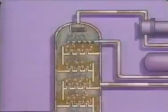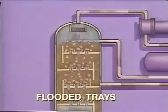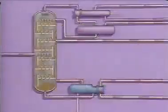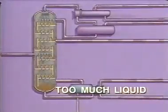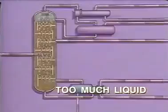There may be several different reasons for this, so an operator must develop troubleshooting skills to identify these types of problems. One abnormal operating situation is flooded trays. When a group of trays in a distillation column become completely filled with liquid, the tower is said to be flooded. Too much liquid flowing down the tower can result in flooding. When the capacity of the downcomers and trays is exceeded, liquid backs up in the tower and the column floods.